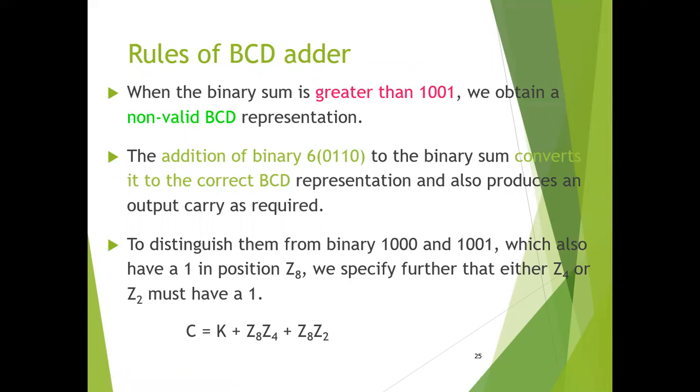The carry generated out of the 4-bit binary number is at the 5th place, which is equivalent to 16. It is actually the difference: the carry generated in the decimal number is equal to 10, and the carry generated in the binary number is equal to 16. So the difference between these two carries is equal to 6.